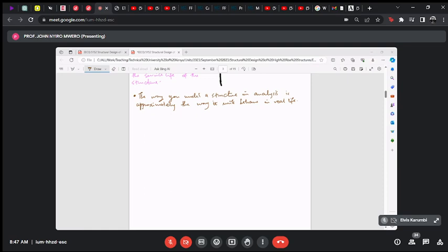Yes, sir, this is Kagonye. Please go ahead. So when you're doing RC construction, is there a way of making them either fixed or pinned? Yes. And I was careful to mention that it's difficult to achieve a perfect pin, but you can actually design the element to behave as if it's a pin.